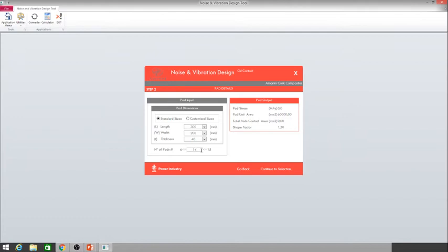So you double up to get a surface area of length 600 against a seating length of 900, per leg. And you see, when inputting the number of pads, the software will calculate pad stress and the shape factor.